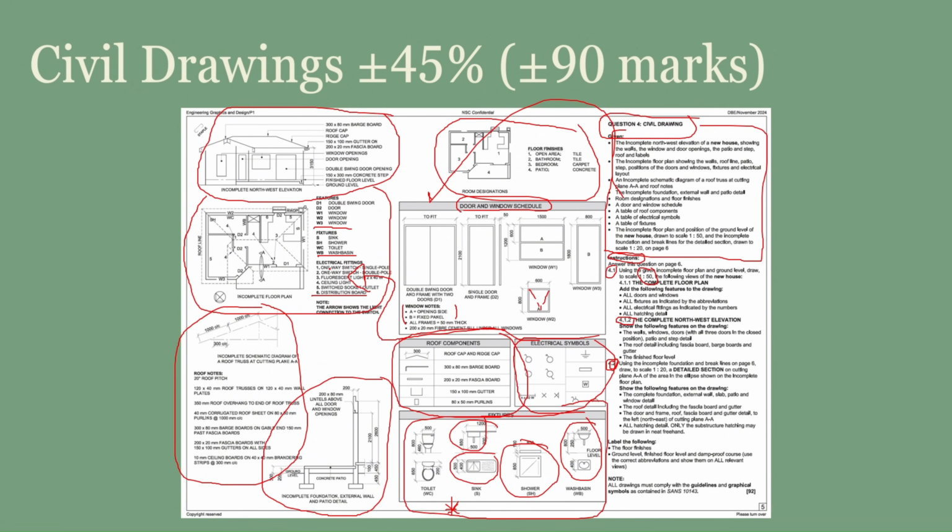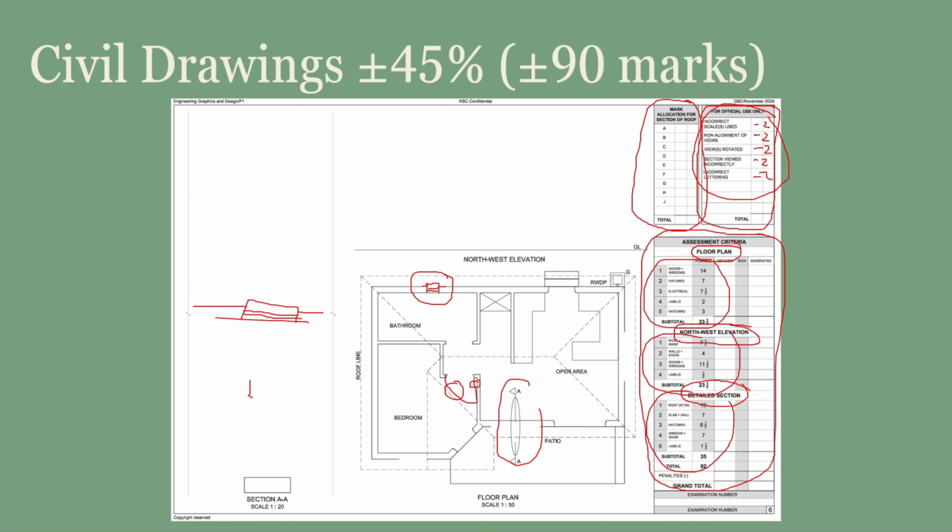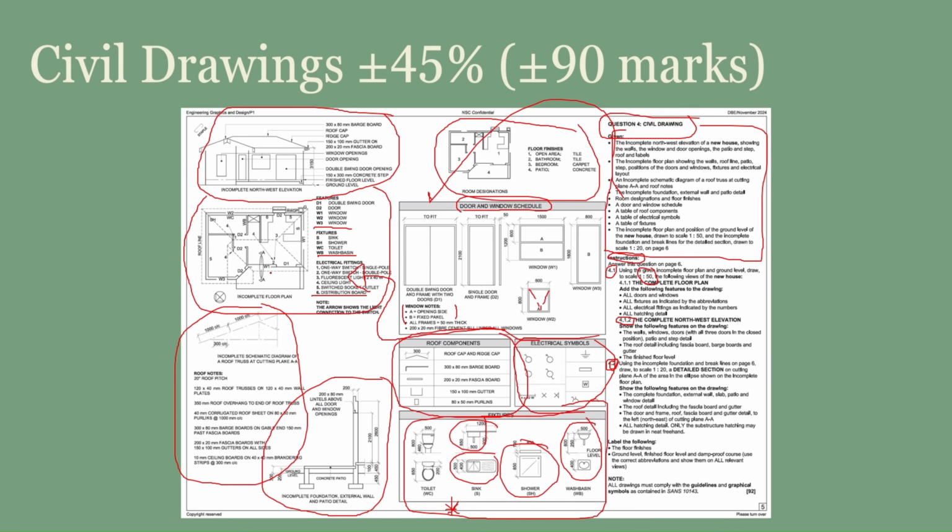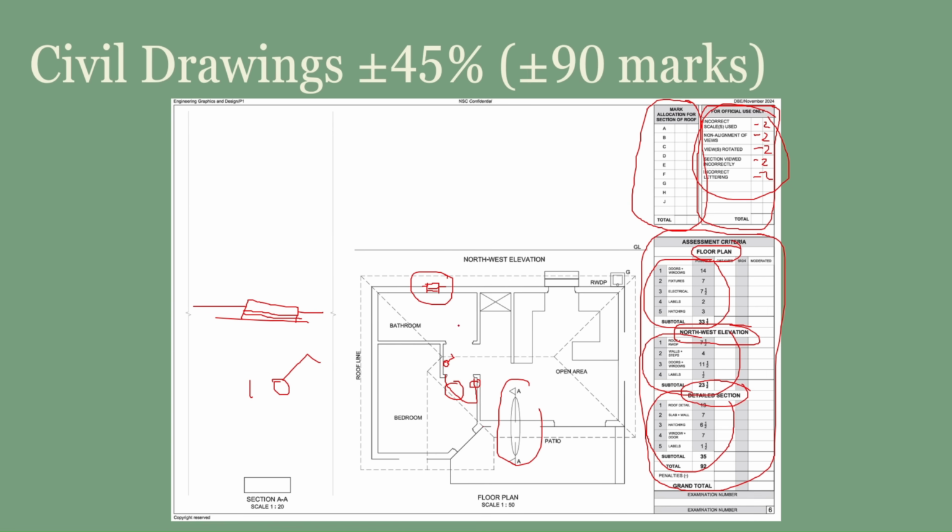So if you start with number 1, you can see number 1 is a one-way switch, single pole. That is a light switch, single pole. So that means it looks like this. It's just a circle with a little ear. And they want to see the full circle, and the circle should touch the wall and the ear should point downwards. Okay, so you need to put that in on all of the ones that they have indicated on this incomplete floor plan. So make sure it's a full circle and that you can see the ear.